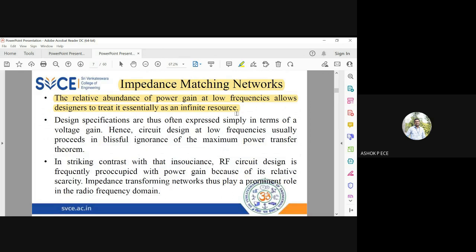So what I will do is design matching networks at the input side and output side, so that these matching networks will ensure maximum power transfer to whatever impedance your ZS or ZL is going to have. Circuits at low frequencies don't suffer with the problem of maximum power transfer because it is mostly met at low frequencies. But in RF circuit design, impedance matching is the foremost condition.